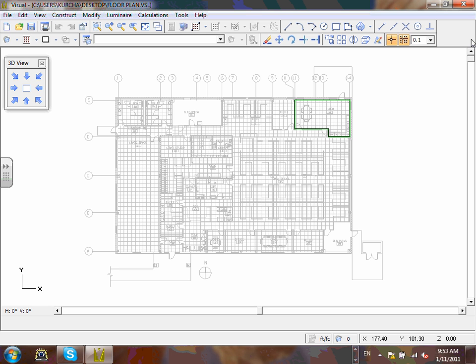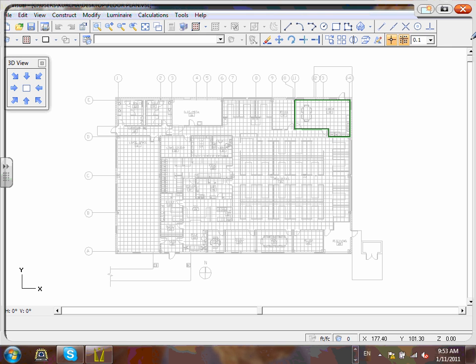I want you to highlight a few things because it might be confusing. Hallways. When you build the hallways, here's my hallway. This is the common area. You're going to remember how we said the common area. We're going to build the solid right up to here. That's a solid for the common area. Now, Brad, you're going to tell me there are no walls there. It's the only way you can get a calculation for the open office: you put a solid exactly like I highlighted. If you guys want to highlight it.